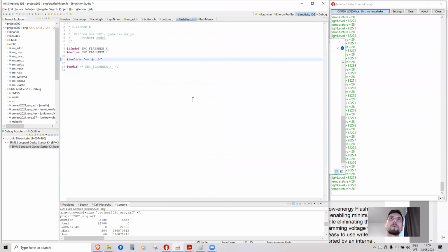And there's some info. Okay, so we will want to write the following API functions in this library. We will call, first of all, initialization. Maybe there's some sequence with which we initialize the memory system controller so that it's able to read and write some data into flash. So let's write it this way: void flash mem init, and void.